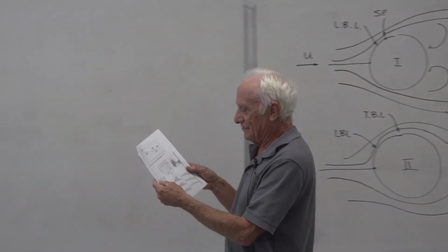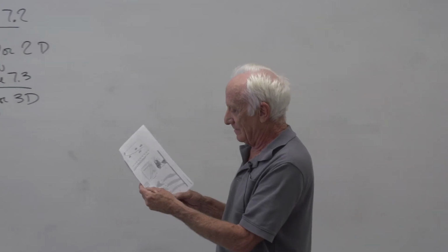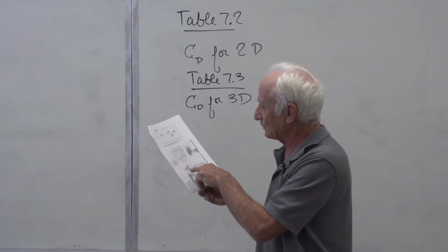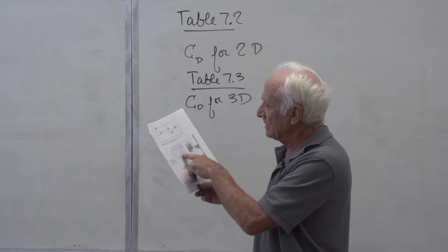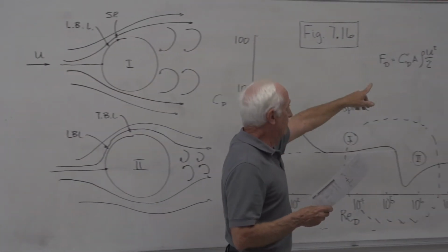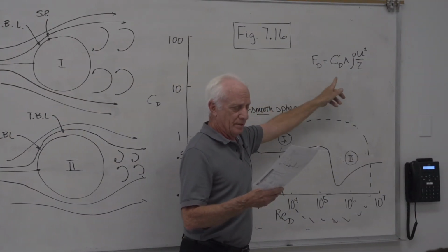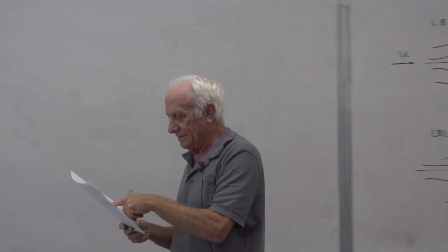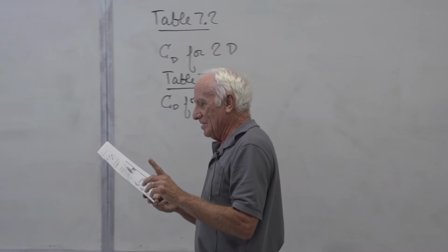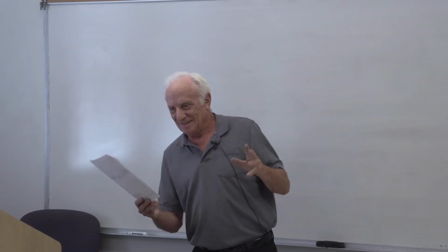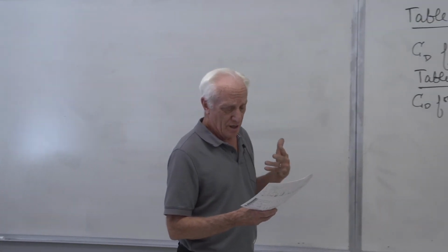There are two kinds of drag that create situations with trucks and cars. They show a truck here, and there's rolling resistance and there's air resistance. Now, air resistance is this guy over here. That's a C sub D. The rolling resistance is the bearings on the tires, the transmission, and so on. When you're going slow, the rolling resistance requires the most power.